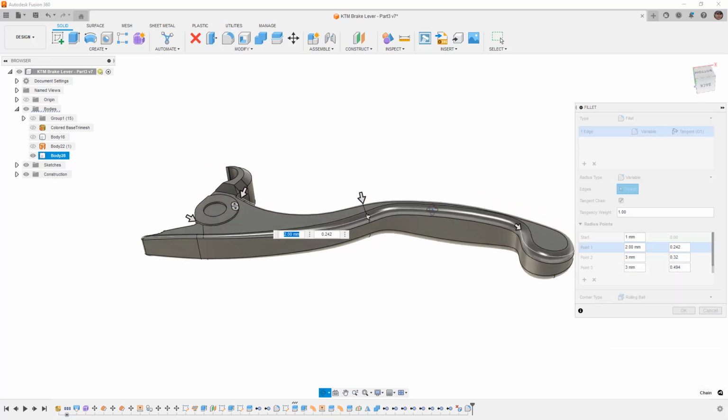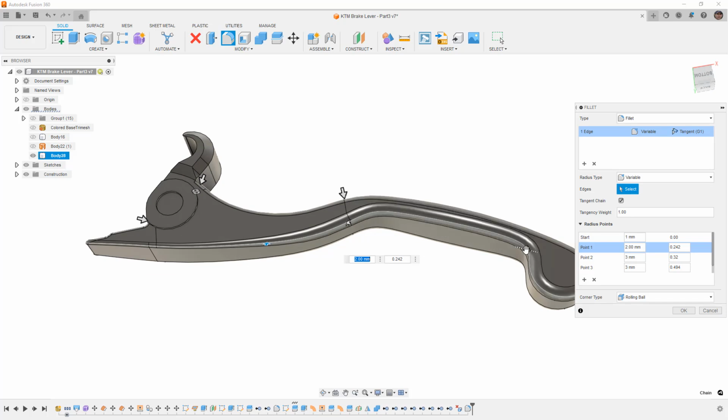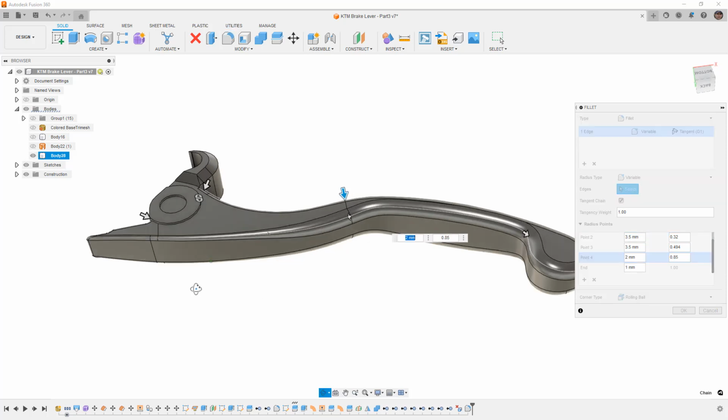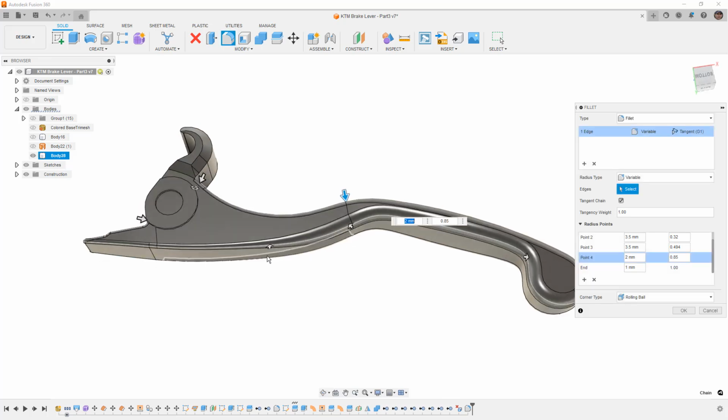So rotate it around and just take a look at the geometry. Remember, we can increase these. I think we had 3.5 here. And for this one, we did the same, was 3.5. And then again, we can move this point if we want to. So looking through our list over here, we're at 0.85 for that point. And this one over here, it's actually the other direction. It's 0.242. So then we would want to decrease this value maybe to 0.23, maybe to 0.22, and just keep moving it until you're happy with the shape.